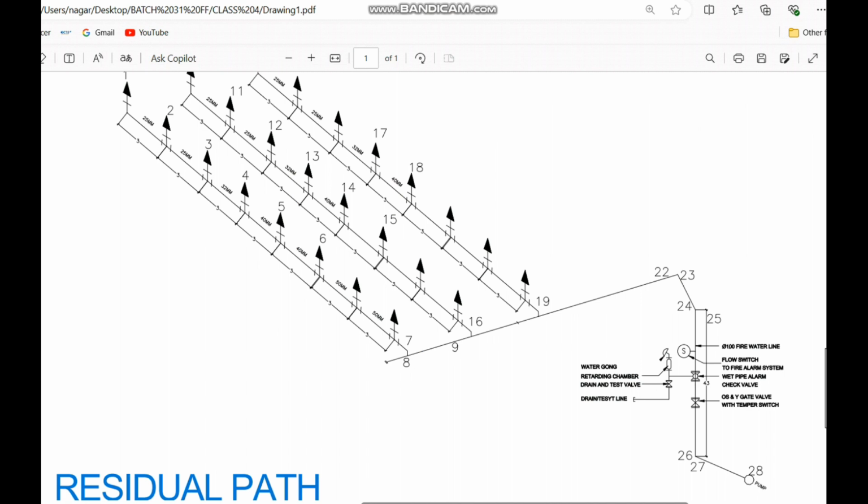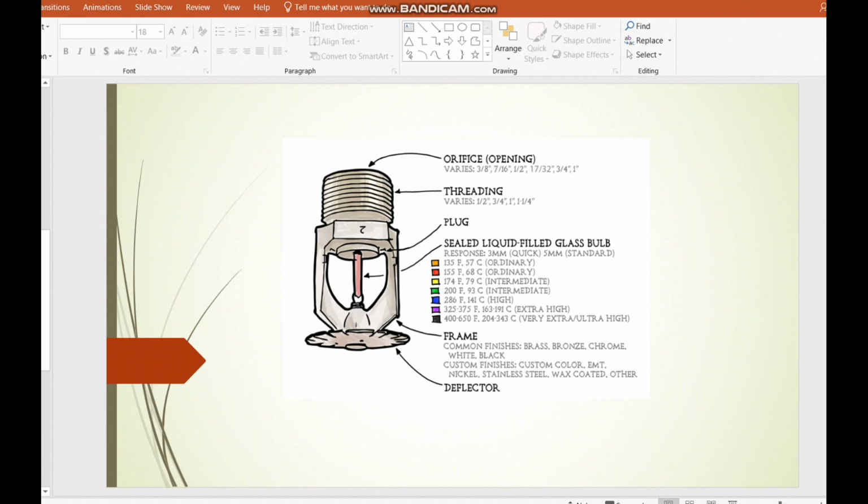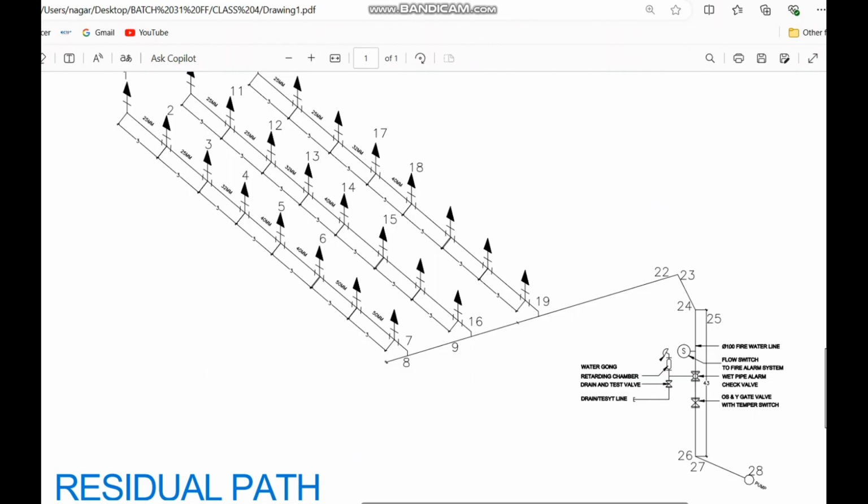Normally, the municipality water is collected in the firefighting tank. From the firefighting tank, using the fire pump, it is distributed throughout the system. So if you have any dust particles in that water, they will go into the firefighting system. And for example, if I take the connection directly from the cross main to a pendant line, you know that a pendant sprinkler has a very small orifice size. If you see the orifice opening here, the size is very small. So if any dust particles block the pendant sprinkler, then at the time of fire we cannot see the water coming out from the sprinkler.